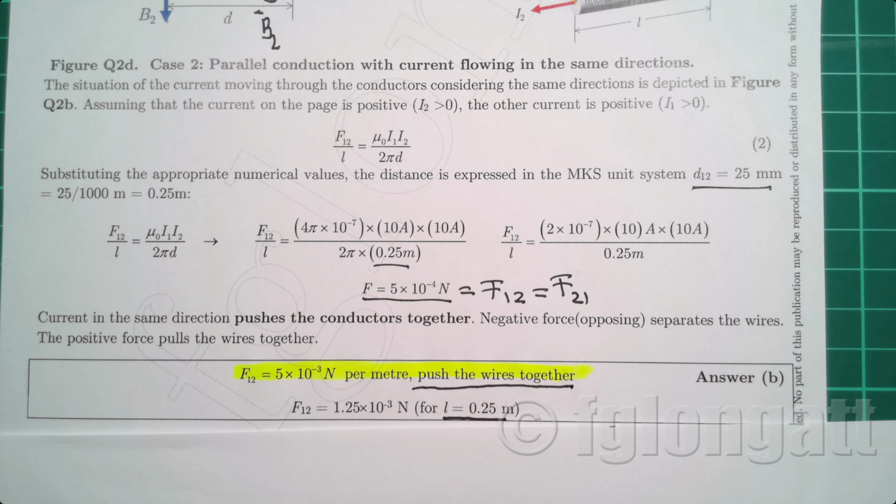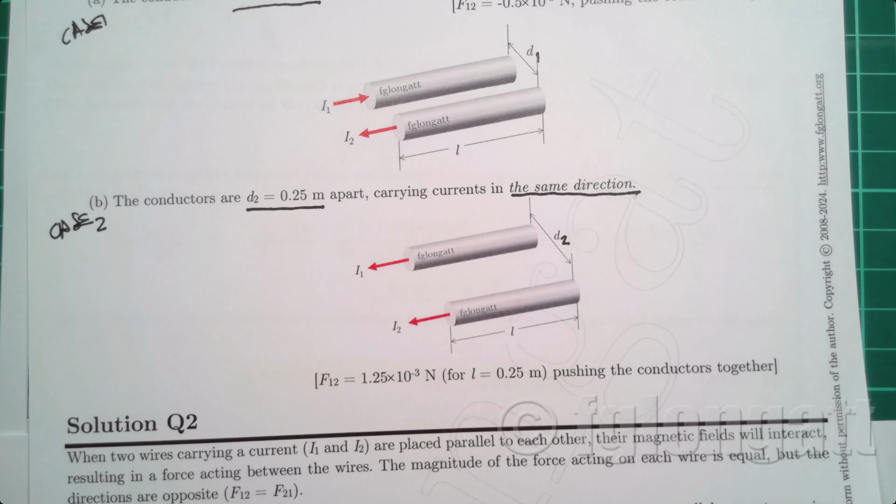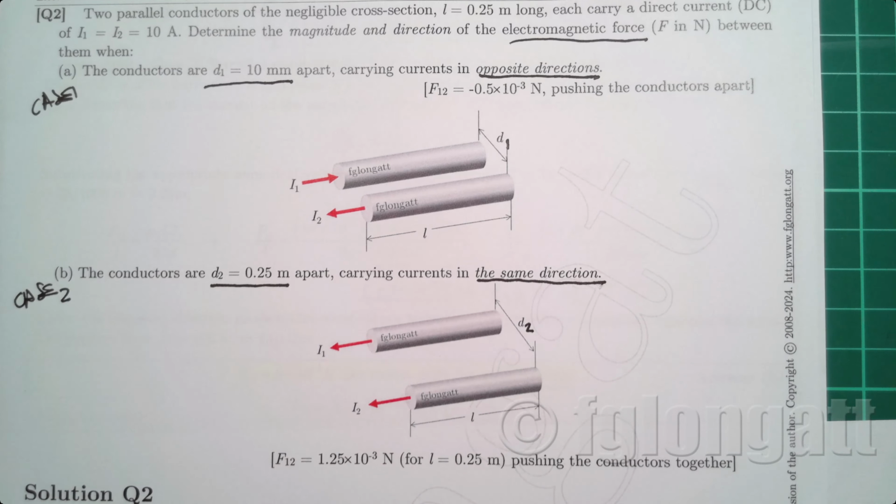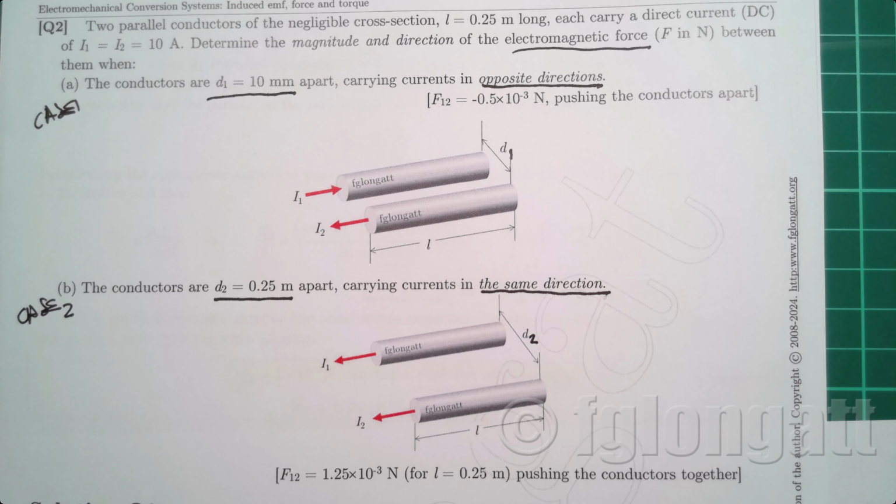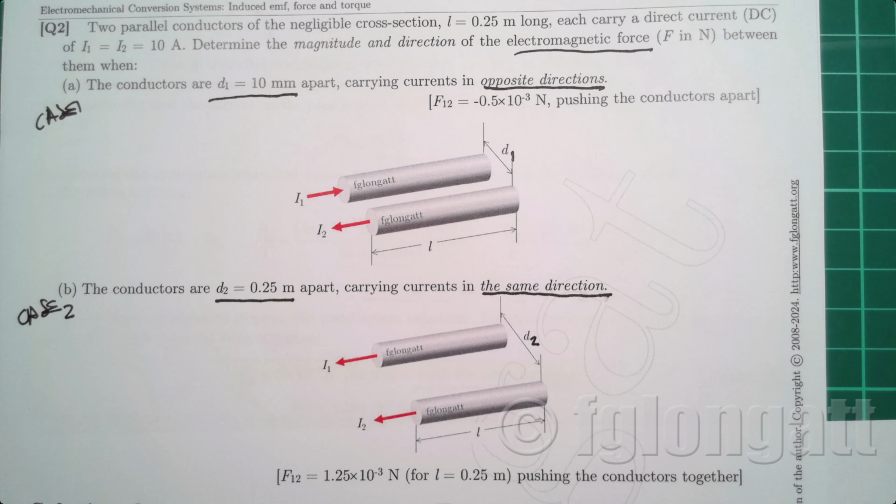To conclude, this is a very basic but very important example, because as you can see, the direction of those currents defines the direction of the force interaction. In some cases you can create attraction, and in other cases repulsion. You will find these very basic principles when we are working with generators and motors, and in many other places, like transmission lines, transformers, or even substation bus bars.